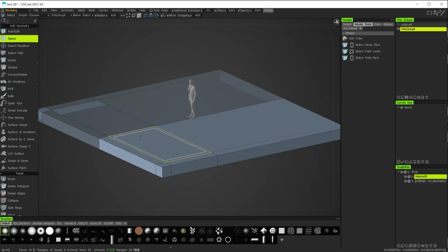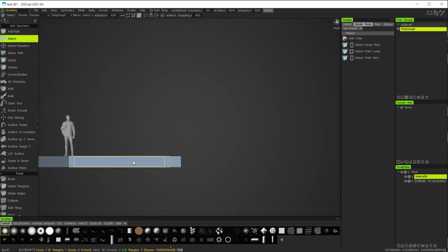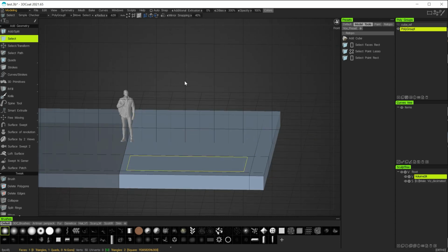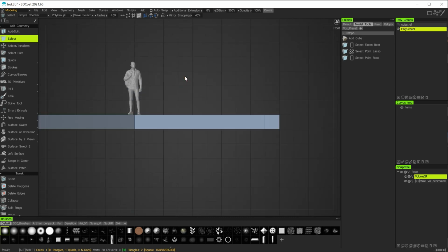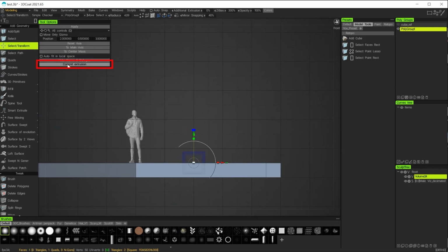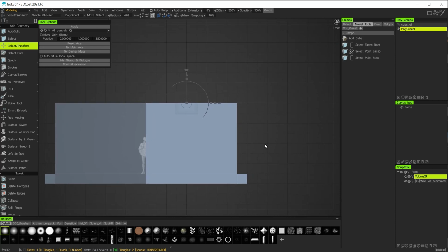So I want to create this front wall now, and I'll need to select this poly here, and I'll snap to the front view and show the grid. So how far do I want this polygon to extend upwards? We'll select the select tool here, commit an extrusion, and snap so that we can extend this wall up.